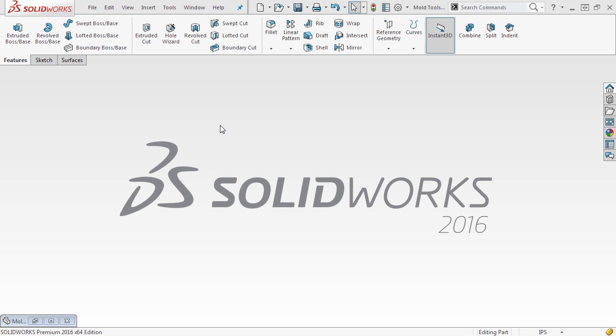So the design intent is really what the part needs to do, what it needs to hold, what its function is, and so on. And the reason the design intent is important, not only from a design aspect and figuring out how pieces move and work, but it also helps you plan things like wall thickness that you need, or material selection, or whatever the end application is. If your end application is a part that sits outside in the sun or the weather, it's going to be a very drastic difference in terms of wall thickness and construction and draft angle and just the overall quality of the part, as opposed to something that's going to be very small, very consumer, handheld based, and so on.